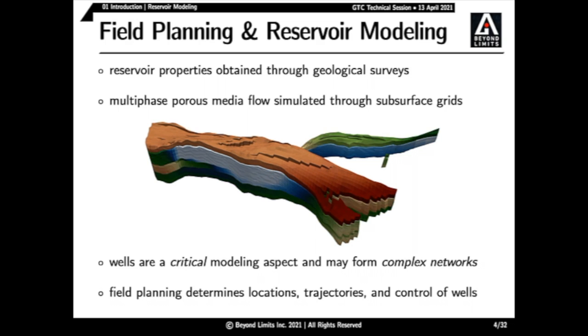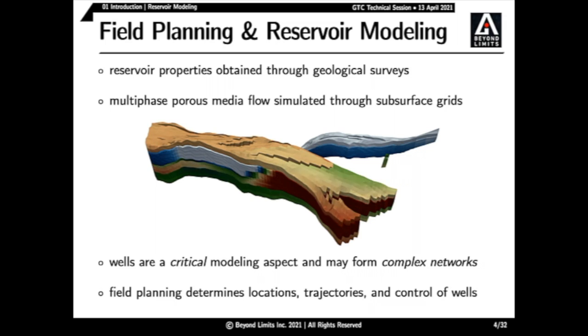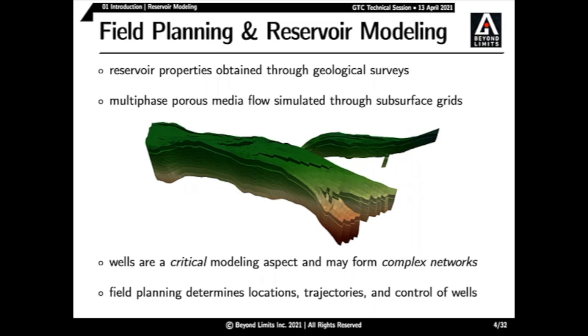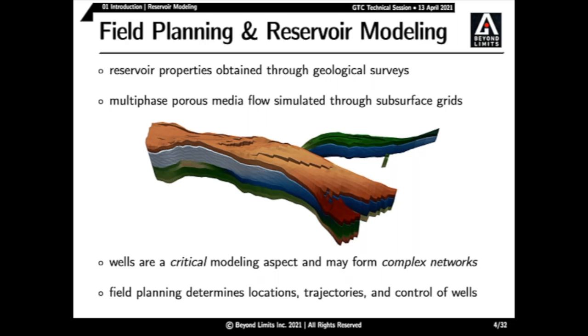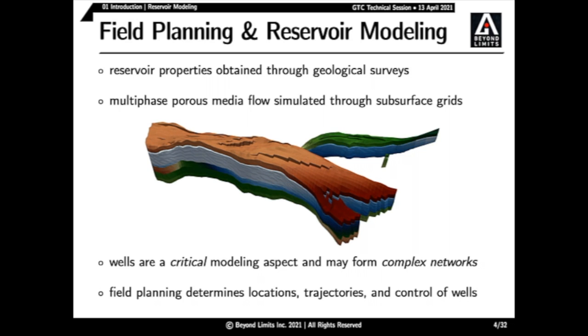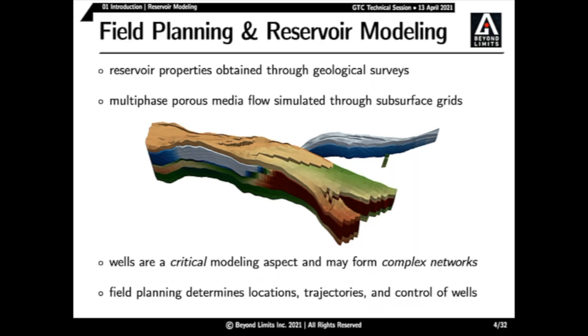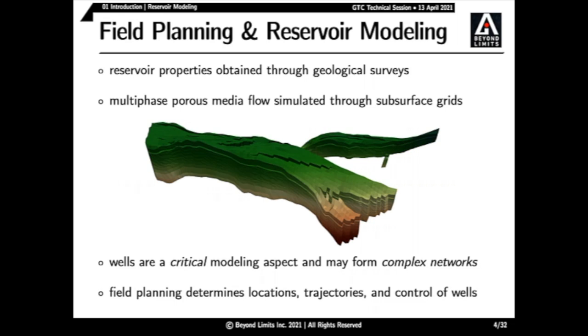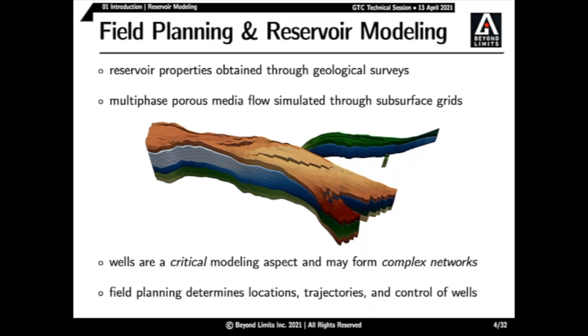Once this is done, multiphase porous media flow or reservoir simulations are performed to understand the mechanisms of fluid transfer and the pressure distribution within the reservoirs. Wells, which are used for production to extract hydrocarbons or injection to increase pressure and encourage the flow of hydrocarbons, are modeled as line sources and sinks within the reservoir simulations, forming algebraic constraint sets that couple to the original PDEs. Now, these are a critical modeling aspect when it comes to reservoir simulations.